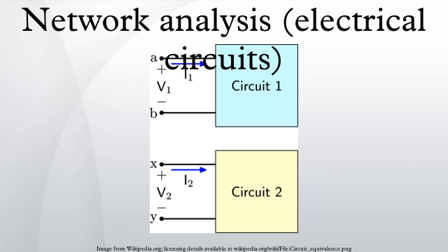However, this is rarely done in reality because, in many practical cases, ports are considered either purely input or purely output. If reverse direction transfer functions are ignored, a multi-port network can always be decomposed into a number of two-port networks. For lumped components, where a network is composed of discrete components, analysis using two-port networks is a matter of choice, not essential. The network can always alternatively be analyzed in terms of its individual component transfer functions.